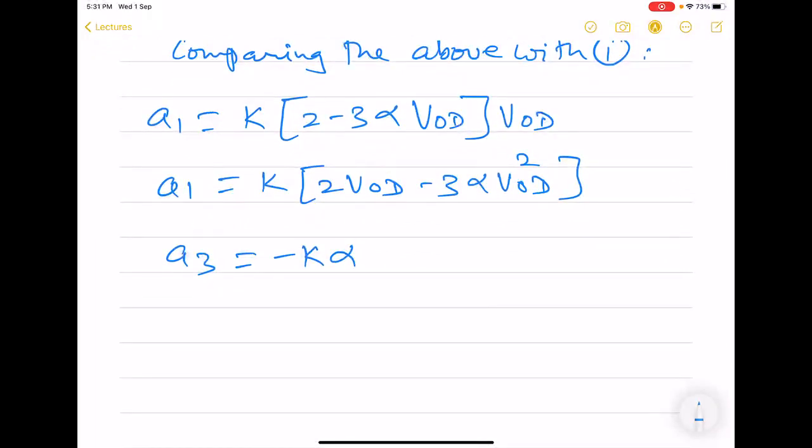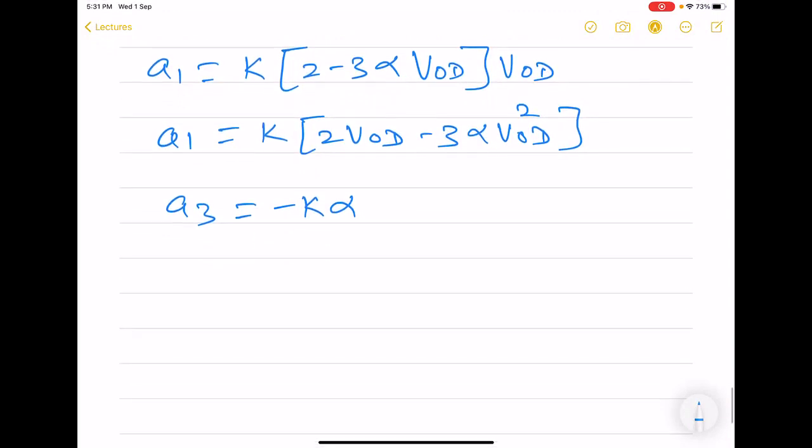And we see that IIP3 and 1 dB both depend upon the ratio of A1 and A3. So let us define a quantity R as magnitude of ratio of A1 and A3, because this is what we will be encountering very often.